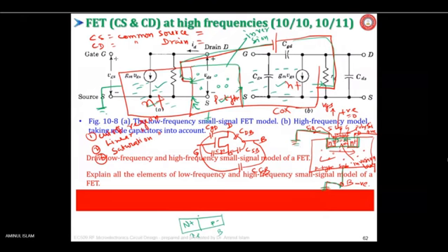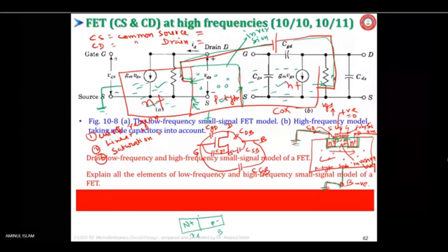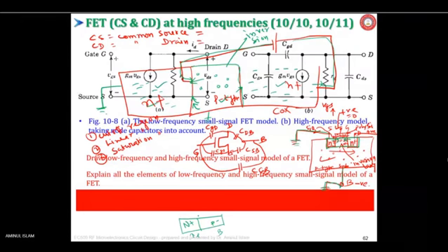Sir, is it possible that electrons from the N side that is grounded will move to the P side, which is also grounded? Yes, sir. But according to me, the N channel is formed from the P substrate only. When positive bias is applied at the gate, holes will be repelled to the opposite side, electrons will be attracted towards the gate, and the N channel will be formed. How will electrons be crossing?